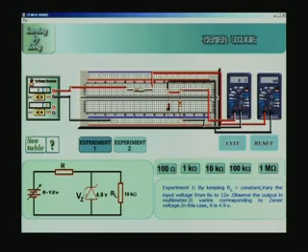These are called two different characteristics of a regulated voltage supply. One is called line regulation, when I change the input voltage and see whether the output remains constant. When I change the load and keep the input constant, it becomes load regulation. Line regulation and load regulation are two important characteristics of a good regulated power supply. That is what we will do first as an experiment. Later on we will try to understand a little more about these things.